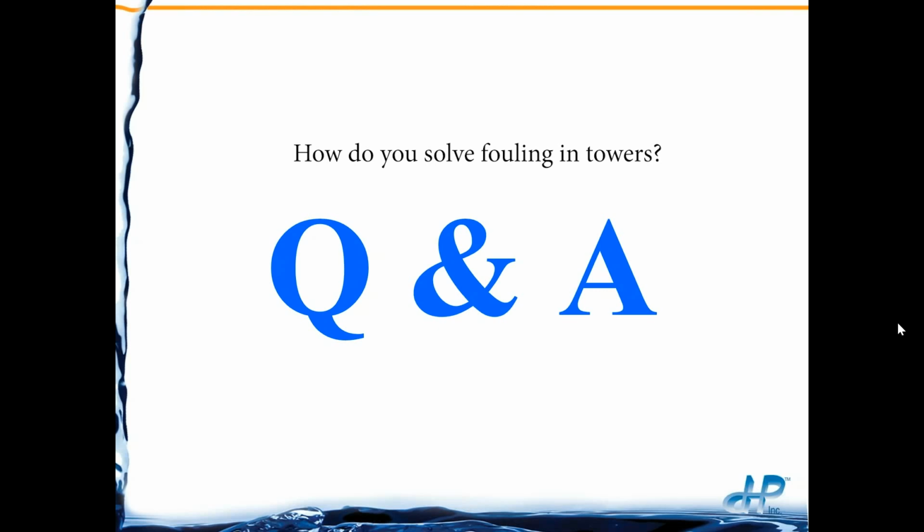Cleaning towers in place does not work really effectively, even though if it's calcium carbonate, you can acid wash it and circulate it, as long as the tower was designed properly to take the chemical washing. Without that, you could just damage the tower. So it's typically best to remove the packing.